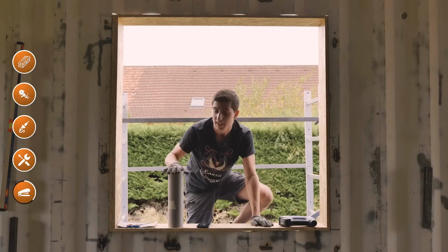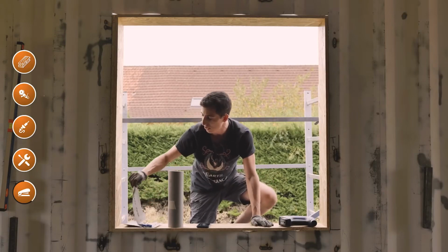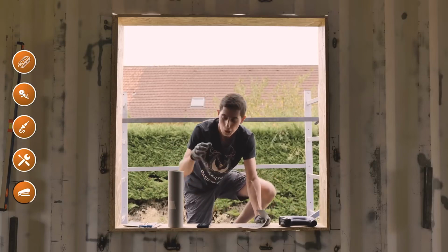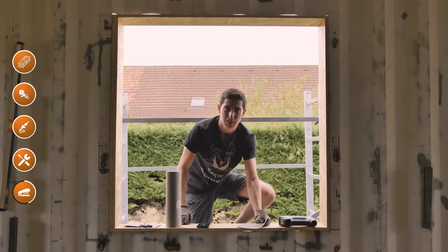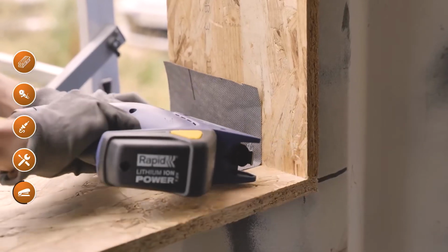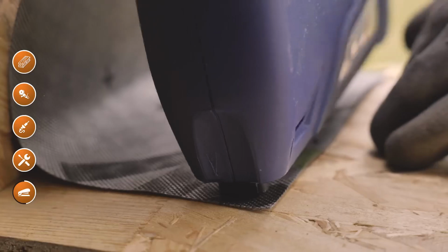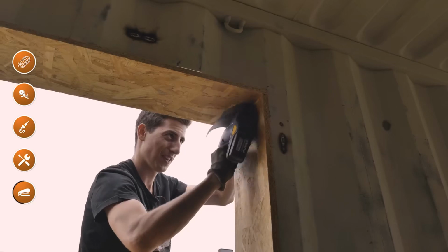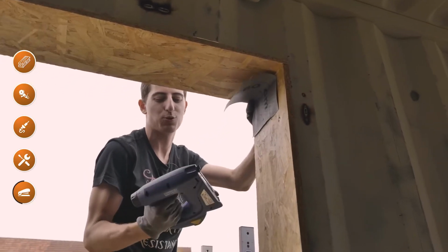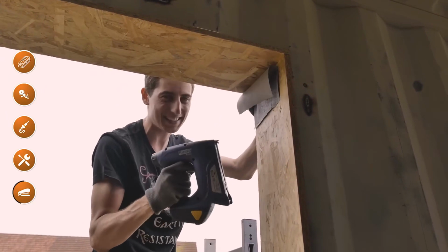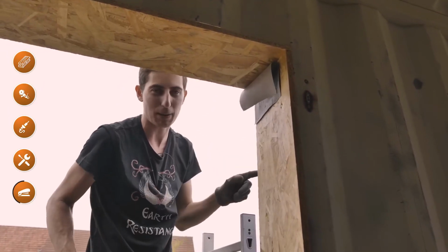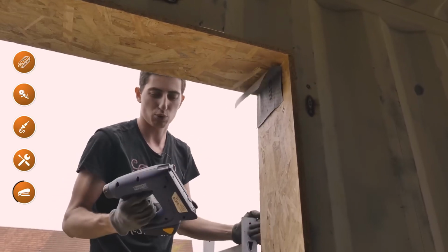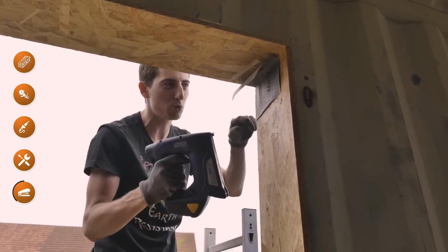But before stapling this big roll, I'm going to staple small reinforcements in each corner to further waterproof my oriented strand board. There you go, let's get started. Quick side note, I treated myself. I bought myself an electric stapler because I'm going to have a lot of rain barriers to staple for the windows, but also later on all the insulation throughout the house. So it's worth investing in a good tool.